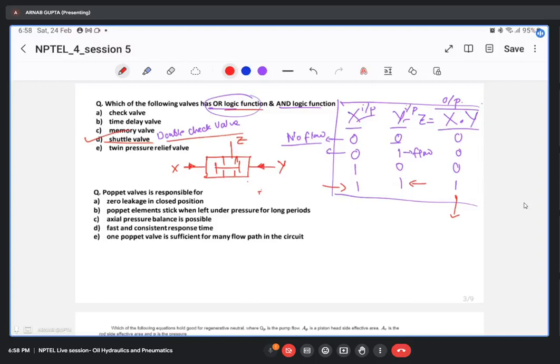This is again necessary. Like you want to put an additional security to your hydraulic system. Security means suppose there should be some switch that needs to be turned on simultaneously. There needs to be two switches. Suppose one safety switch is there and another on switch is there. So you need to press both the buttons to actuate the particular system.